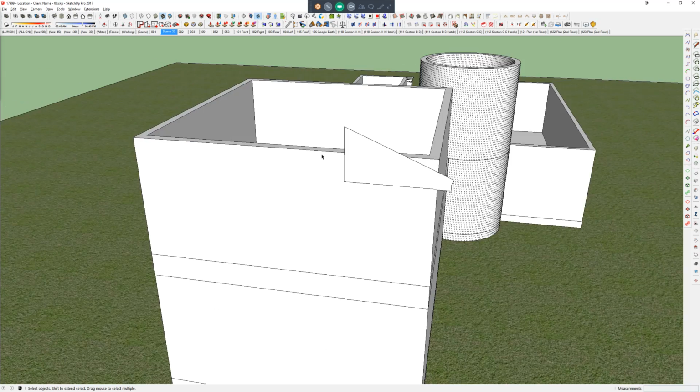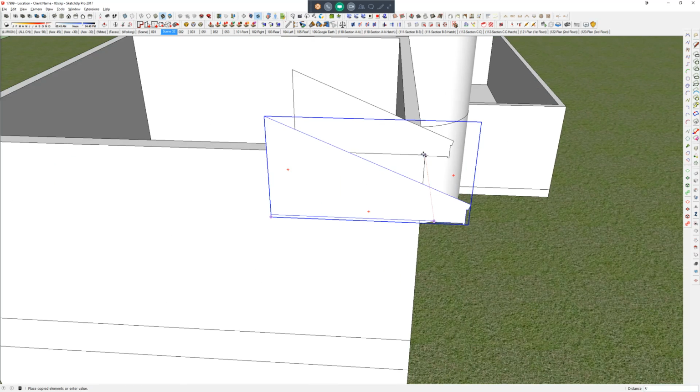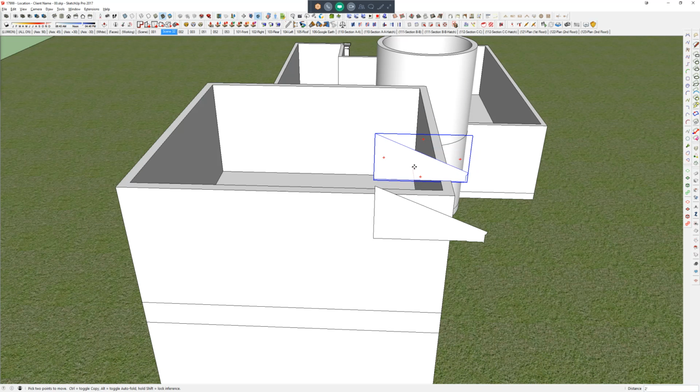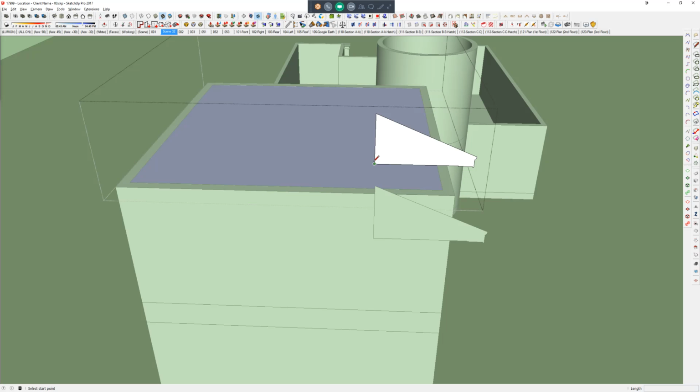And so if you build the roof and you get something funky in it, usually there's something wrong with your polyline to begin with. So it's just one of those red flags to be aware of, because there's nothing worse than finding an error way down the road that you have to repair a lot of things.